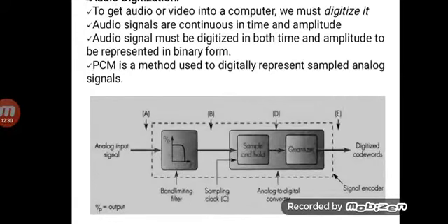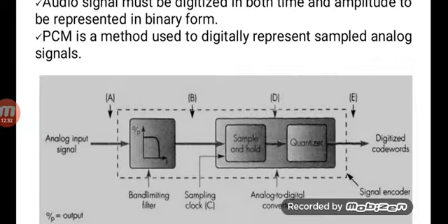the similar kind of process that we used for analog to digital conversion. So obviously we'll be going for sampling and holding, followed by a quantization level. Here the quality of the audio signal depends upon how you go for sampling of your analog audio signal. If you go for a higher sampling rate, obviously the quality of the audio signal will improve. Again you need to go for better quantization levels,